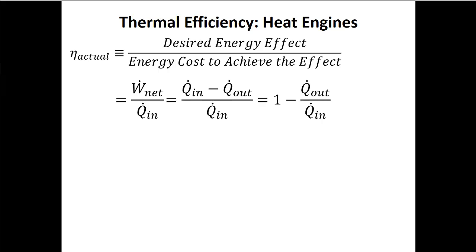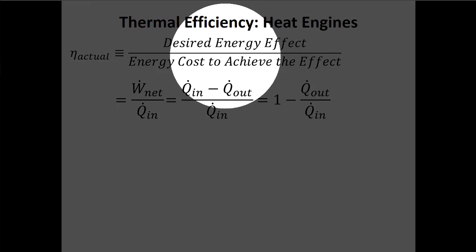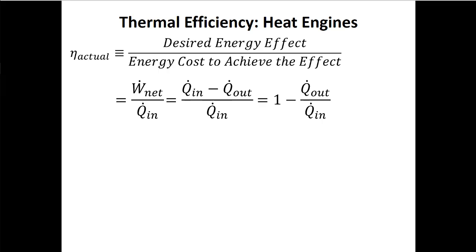So this is the thing. Efficiencies are percentages, and it's not like playing football or hockey or something where you can give 110%. Your efficiencies can never be more than 100%. If you do an analysis like this and your heat engine has an efficiency of 110%, it means that you made a mistake somewhere in the data that you were recording or in the math that you were doing. It's impossible to have an efficiency more than 100%, because that would mean you're producing more energy than you put in, and that's just not possible.